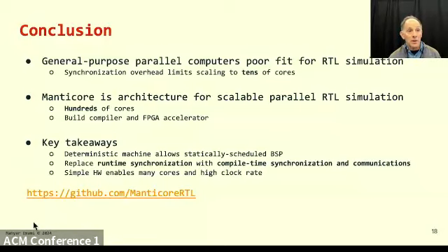So how do you implement the visibility into this? Well, you have the front end, and you basically communicate with the Manticore, and we play a clocking trick so that we stop the computation while the communication is going on. So it appears synchronous, so you can see the state.